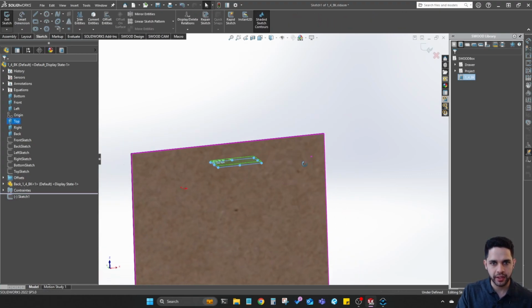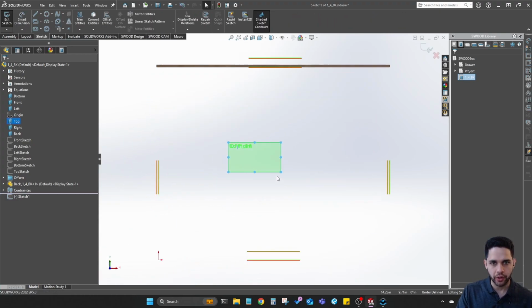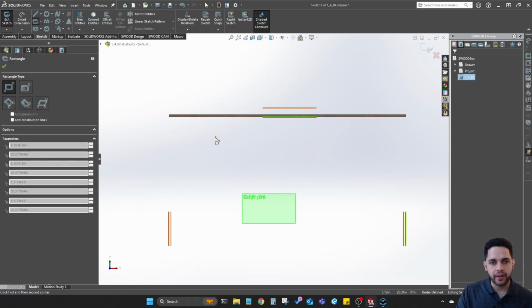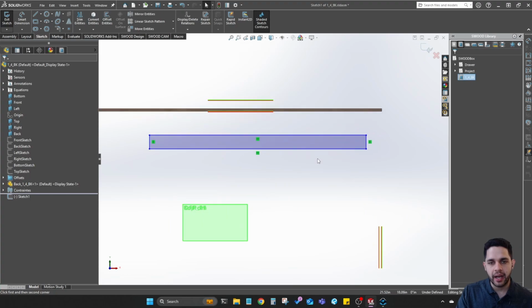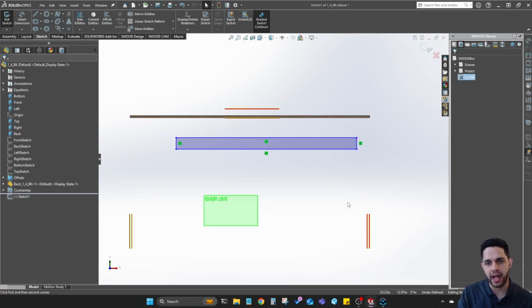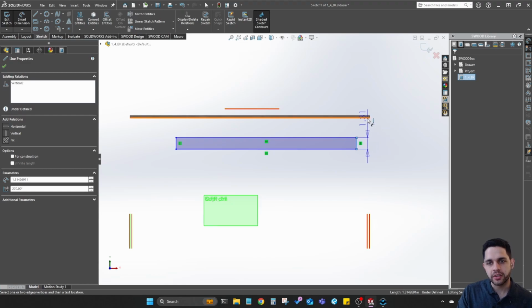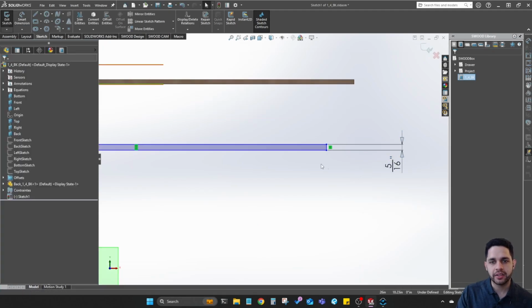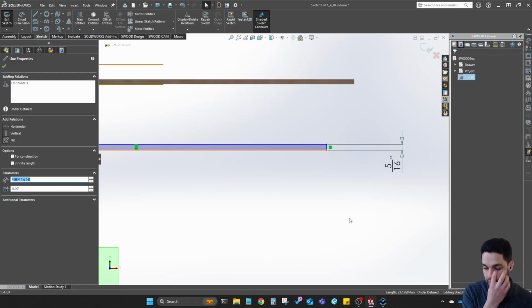We'll do that, click on sketch, and we're going to go normal to so we can see the top of it. And the way that we'll do that sketch, and this is just from experience that I've had at previous jobs, since this is a 1/4 inch panel, I'm going to make this extrude cut 5/16. So that way it's just slightly bigger than that 1/4 inch material.